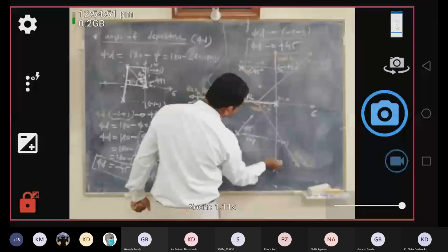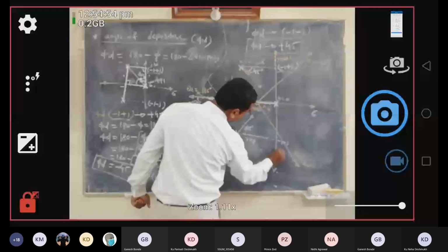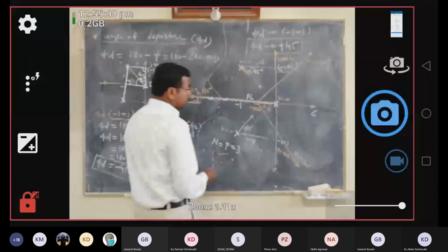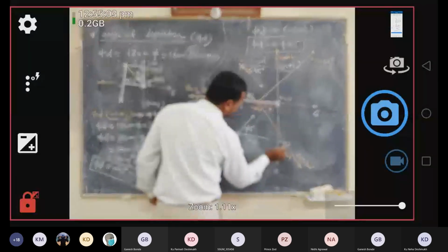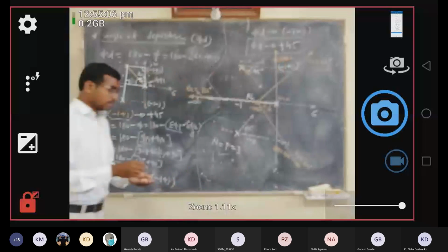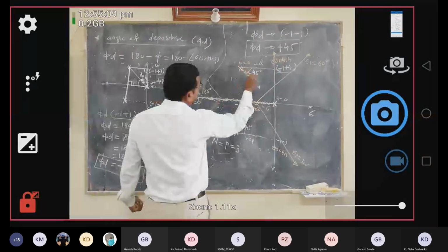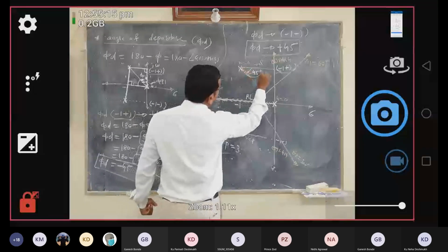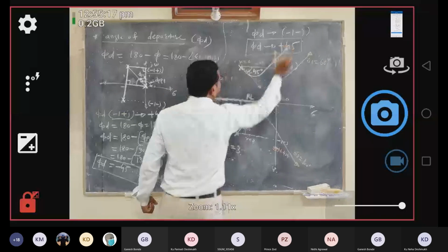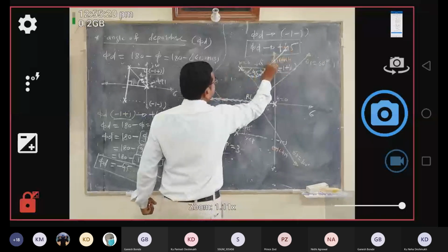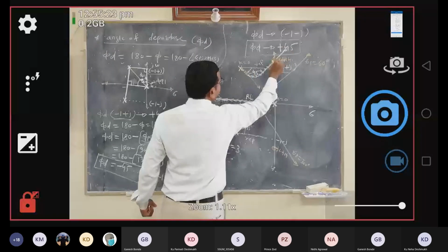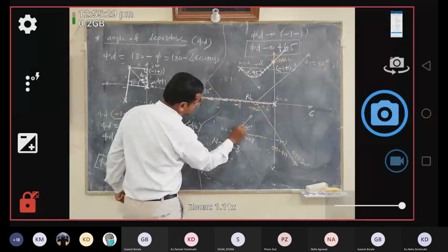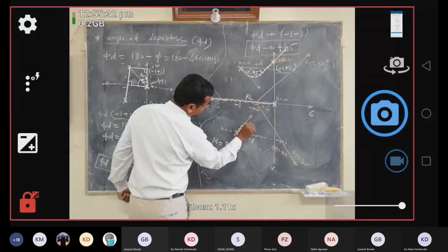So here is your minus 1, so somewhere here j 1.414 and minus j 1.414. At this point your root locus branches are intersecting with the imaginary axis. Then you just take a small part through this 45 degree angle and change the direction of the root locus branch like this. Similarly, here the root locus may start at k equal to 0 like this, and after that I may change the path like this.